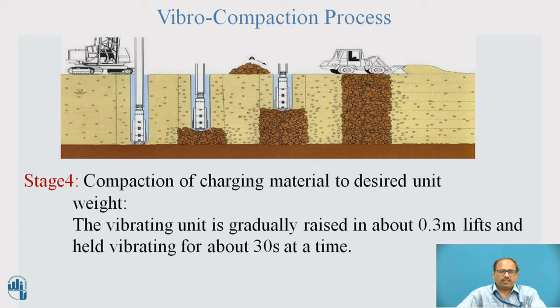Then the minimum vibrating time is 30 seconds at a time. Then again your 0.3 meter is over, then the next 0.3 meter, then again 0.3 meter. So it goes on up to the ground surface, and this is the vibro-compaction process.